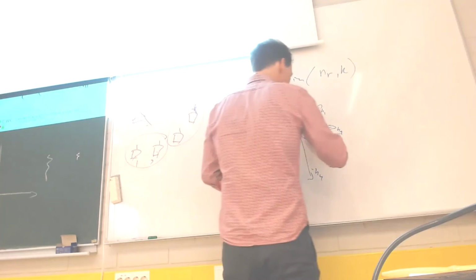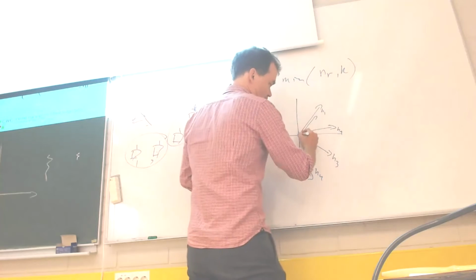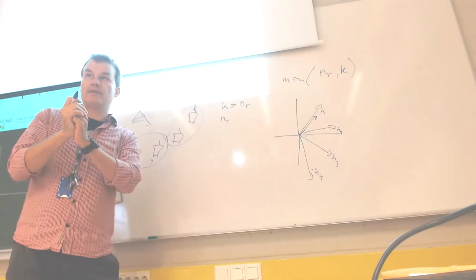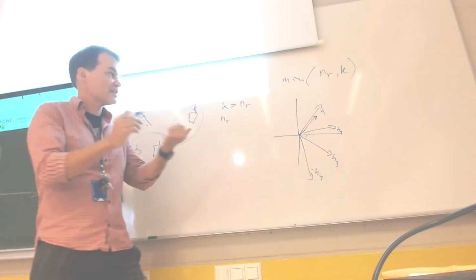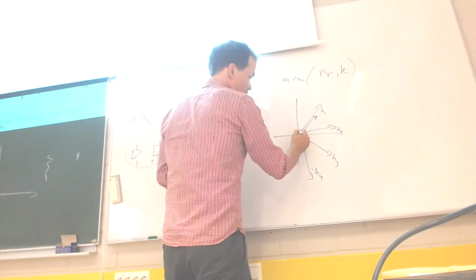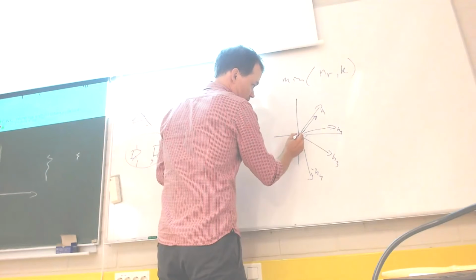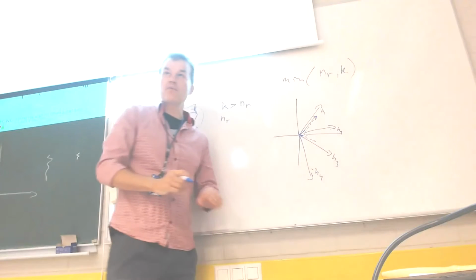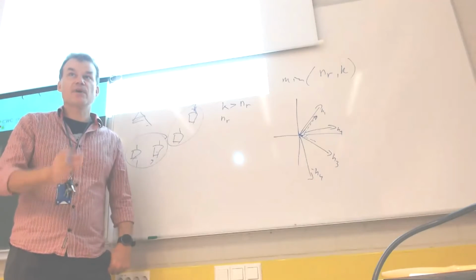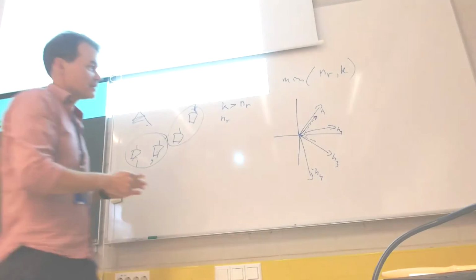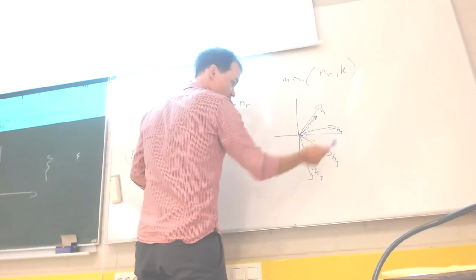If you have, for example, another user 5, which is almost collinear with user 1, this would be the worst possible pairing. After projecting user 1 to the null space of user 5 and the other way around, the gain would be very small, and vice versa. So a good grouping strategy would be user 1 and user 3, and user 2 and user 4, and perform TDMA or FDMA.